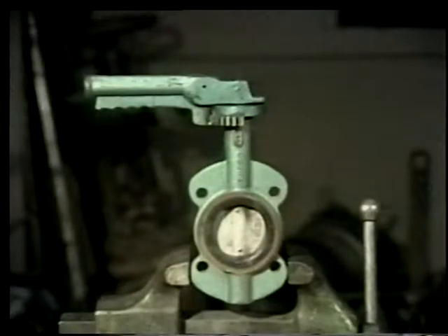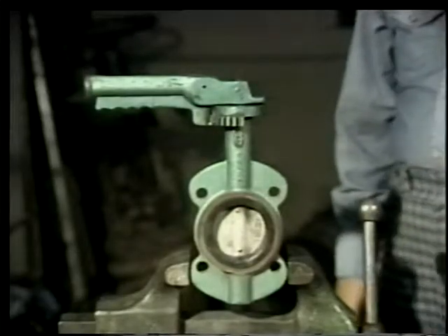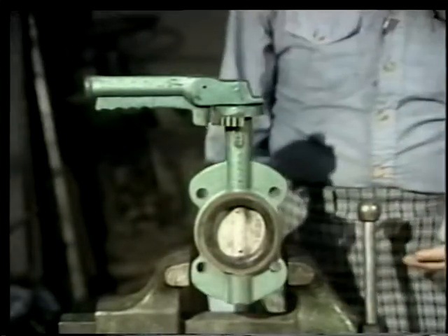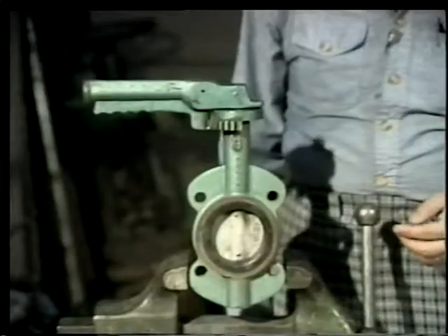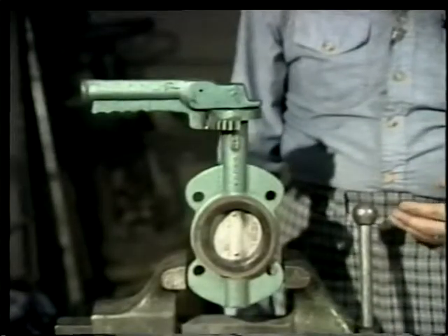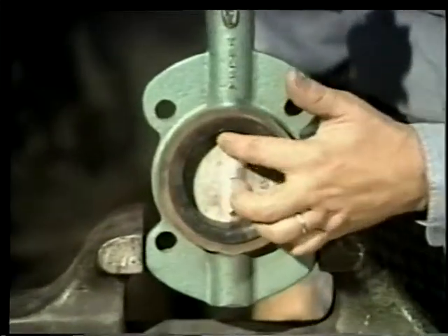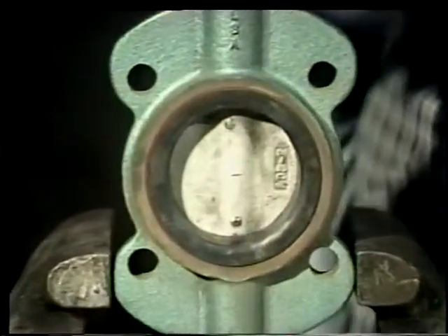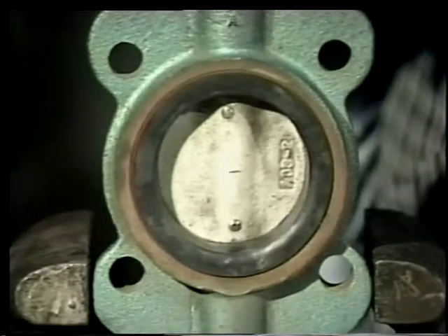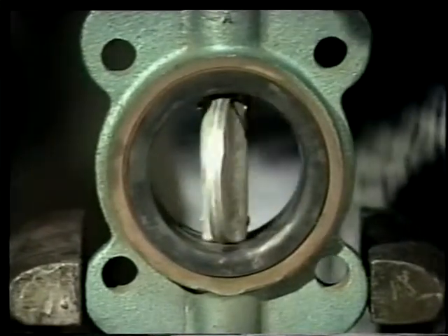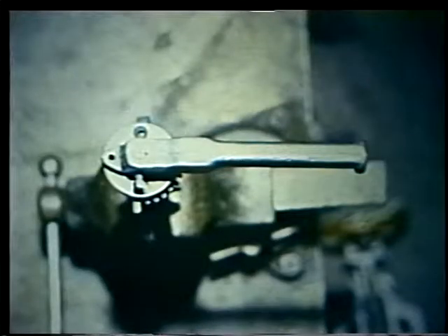This is a butterfly valve. Now, these valves are normally found in low-pressure, low-temperature systems. Butterfly valves are useful on large volume systems where space is limited. The disc on a butterfly valve is the same diameter as the piping it is attached to. When activated, the disc turns 90 degrees from the fully closed to the fully opened position. The position of the butterfly valve can easily be observed. When it's in line with the piping, it is open. When it is perpendicular or across the piping, the valve is closed.